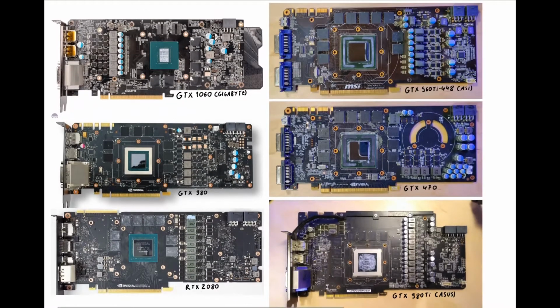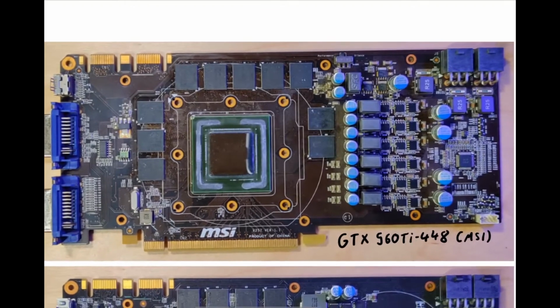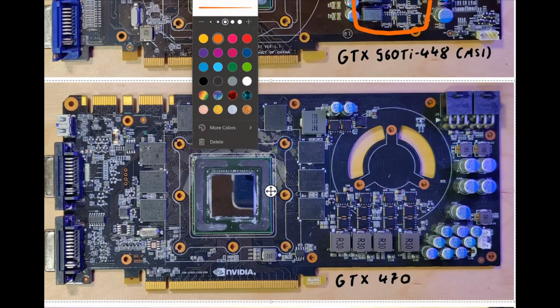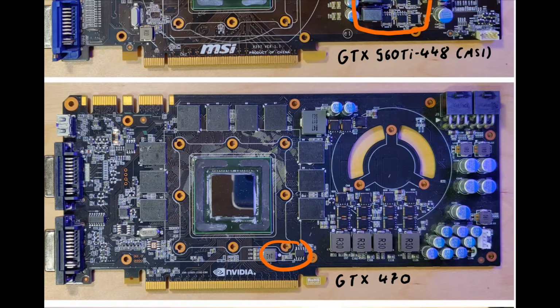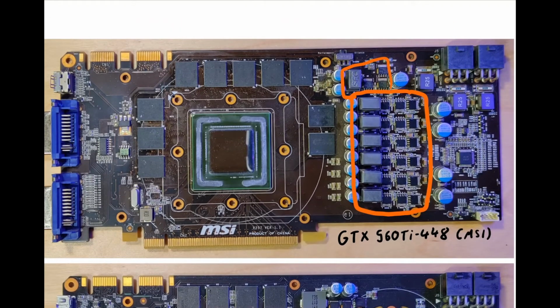And yeah, there are different kinds and ways you can implement VRMs. So the most common VRM will just look like this. You have one big block over here, which is your vCore. Then you have a smaller VRM, which is vMem, and then you will find one inductor down there, which is vPEX. vPEX is not really that important. Like there's another PEX rail. What is important is vCore and vMem, and also VDDCI.